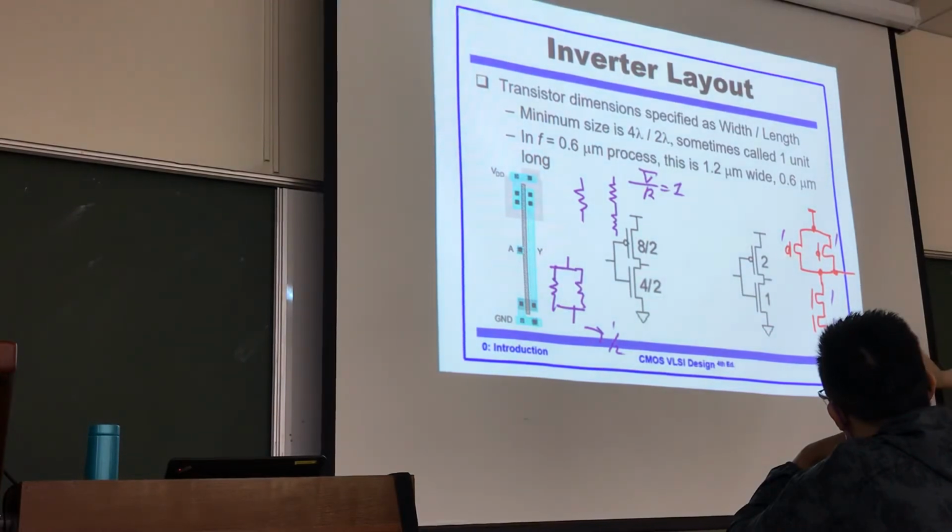Even one PMOS and one NMOS, even the same size, the same channel width, PMOS is more difficult, is slower to turn on. NMOS is easier, is faster to turn on. However, if you connect two NMOS transistors in serial, it just compensates. It becomes equivalent to PMOS and NMOS with the same size.